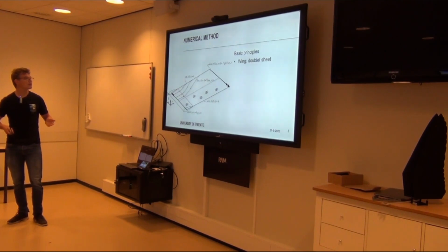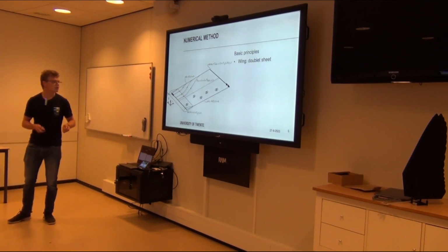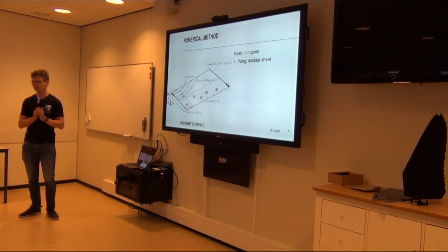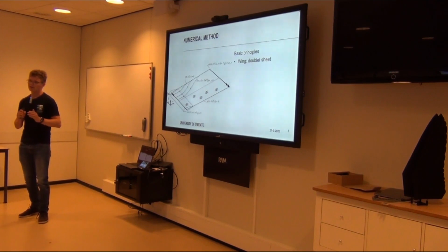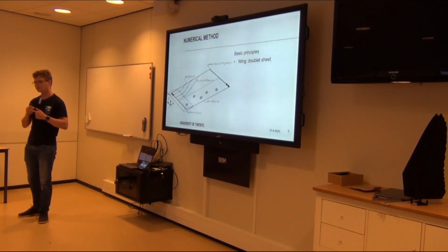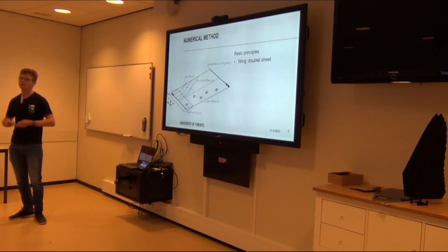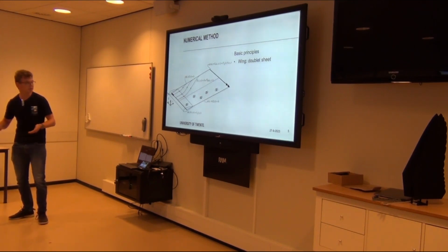And what we did here is we modeled the wing itself, our lifting surface, as a vortex. A vortex that interacts with a free stream, according to Kutta-Joukowski, is capable of producing lift. So there you have a lifting surface.